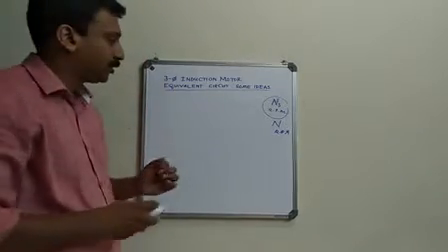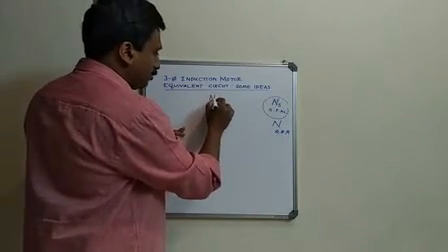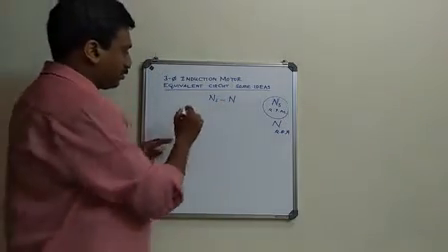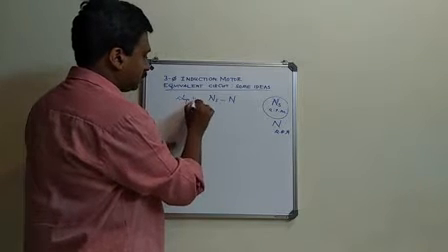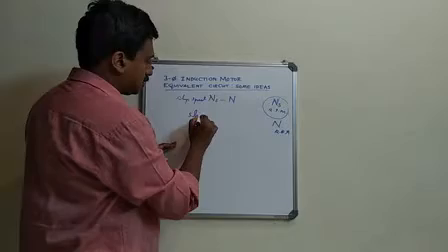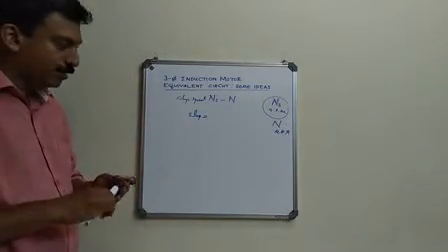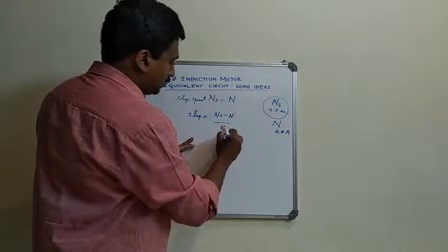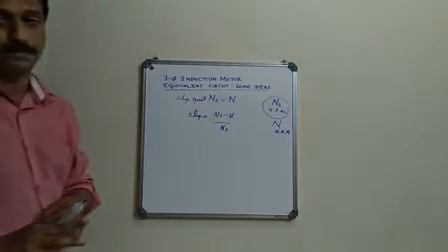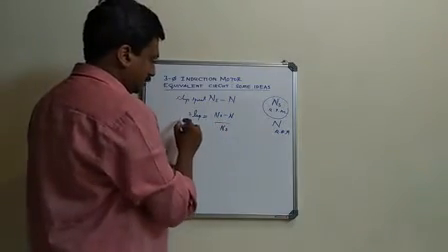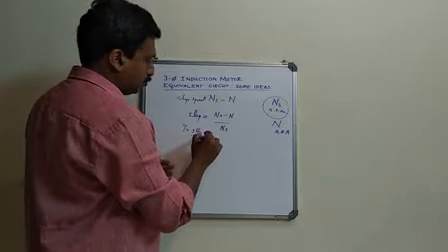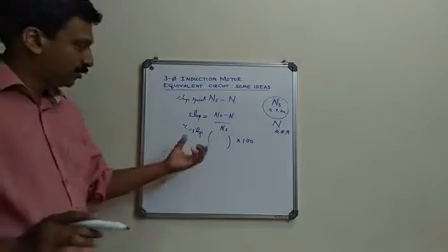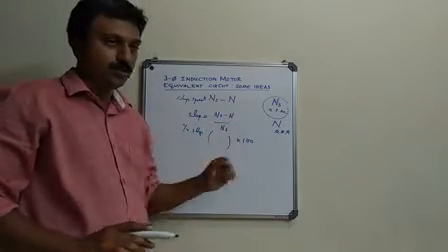Now comes another term called slip speed, given by ns minus n. There is also a quantity called slip, given by ns minus n divided by ns, so it is the slip speed referred to the synchronous speed. This is called s, and if it is a percentage slip, you multiply it by 100. So just understand this is how slip is defined.